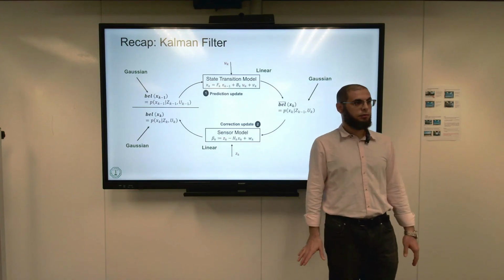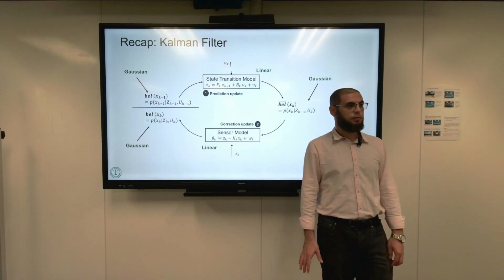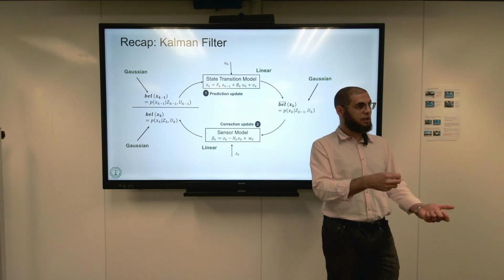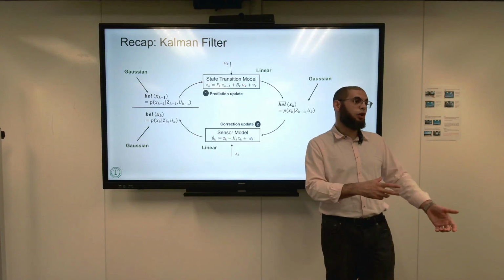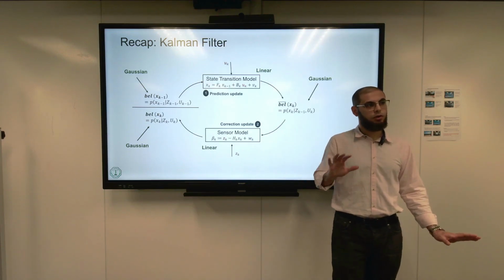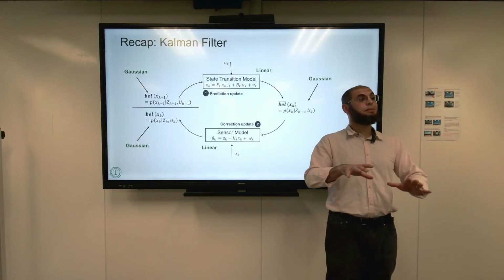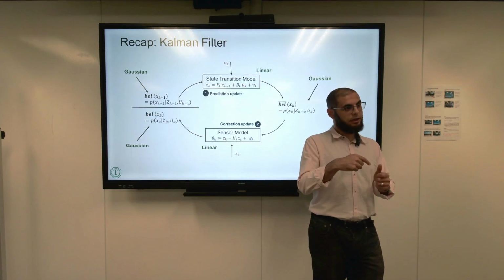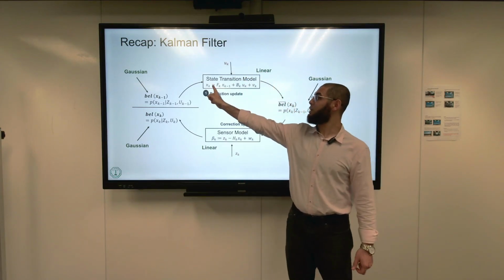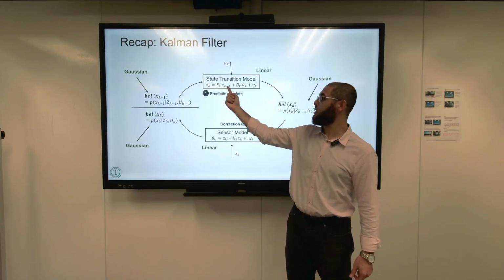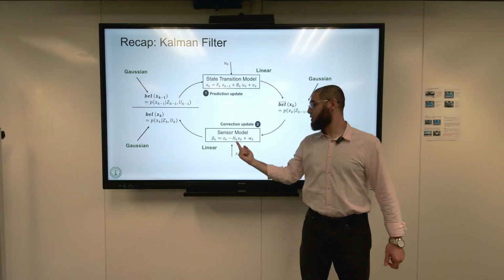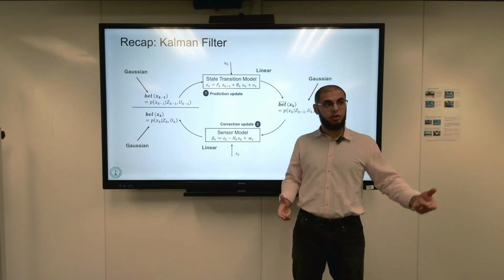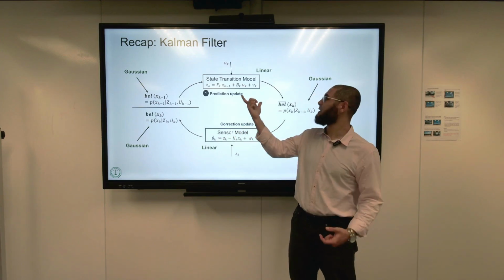So whatever sensor I have, I have to make it the same output in the end? But that's not the same output, right? The IMU will give you accelerations, and the camera will give you velocities. Are they the same measurement? Are they the same state? They don't use the same measurement, but they can derive the same state. They are related to it. Exactly. So the proprioceptive sensor is related to the state through the state transition model. You see the U here affects the X, and the exteroceptive sensor affects the X through the sensor model. Remember, I mentioned this several times, that this is the sensor model and this is the state transition model.